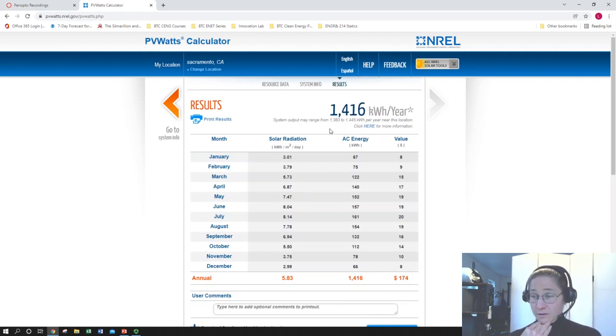So with 1 kilowatt of module STC rated panel production, we can get 1,416 kilowatt hours per year, which is a measure of how much more irradiance this area is getting than STC, because we sure knocked that thing down 22% with resistive losses, which took away electrical energy that we could have gotten from our solar energy.